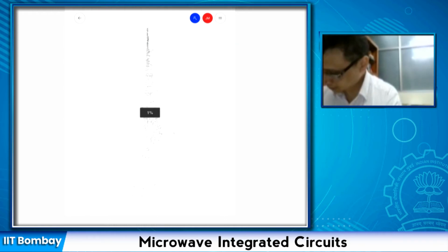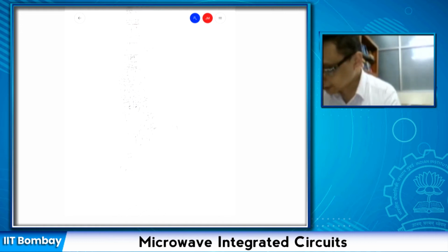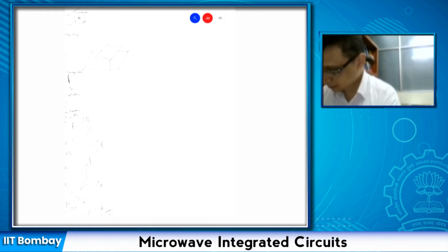Sir, I had a small question. The n will be limited, right? Kc has to be smaller than K, otherwise it will become an exponentially dying out wave, right? Yes, absolutely. And one more thing: we can't take it that beta can go as close to 0 as possible, right? Because that beta should still be above the cutoff frequency. So only till that value of n we can actually tolerate these waves. Yes, absolutely.